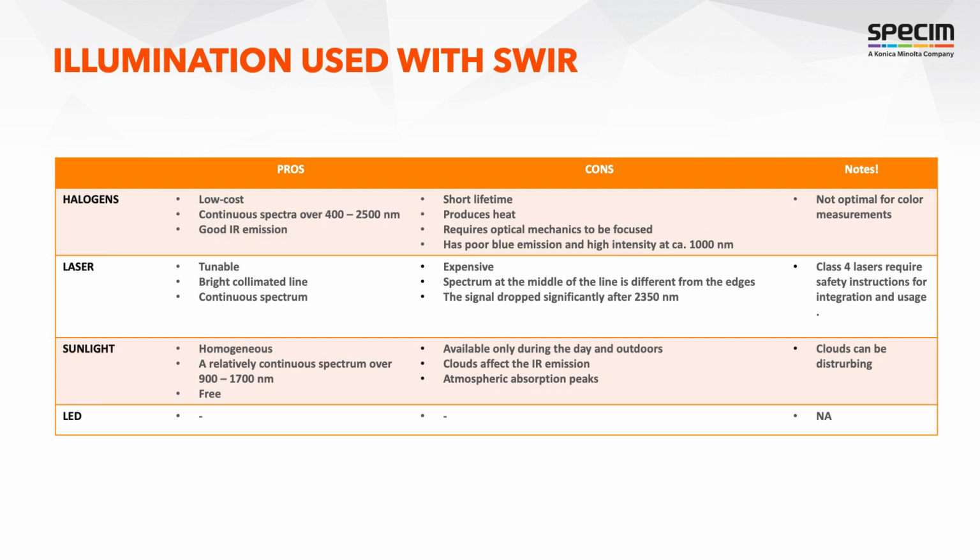Okay, then the laser. We have what we call supercontinuum laser. Personally, I tested one and the illumination was going up to 2350 nanometers. That was pretty good. The only thing you have to be careful about when you deal with a laser is that it's a class 4 laser, so you need to have some safety around.